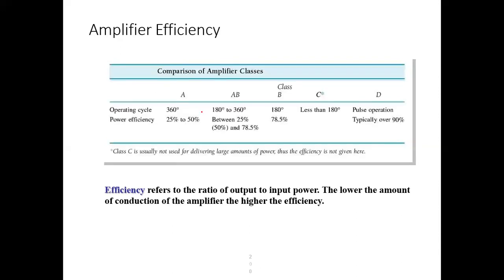So this is the concept of feedback and the power amplifier. Most circuits use negative feedback because we can control the output gain. We do not require more gain, but we require different variable gains. So we need negative feedback, and for high power transmission and high power processing, we need a power amplifier in the different classes: class A, B, AB, C and D.